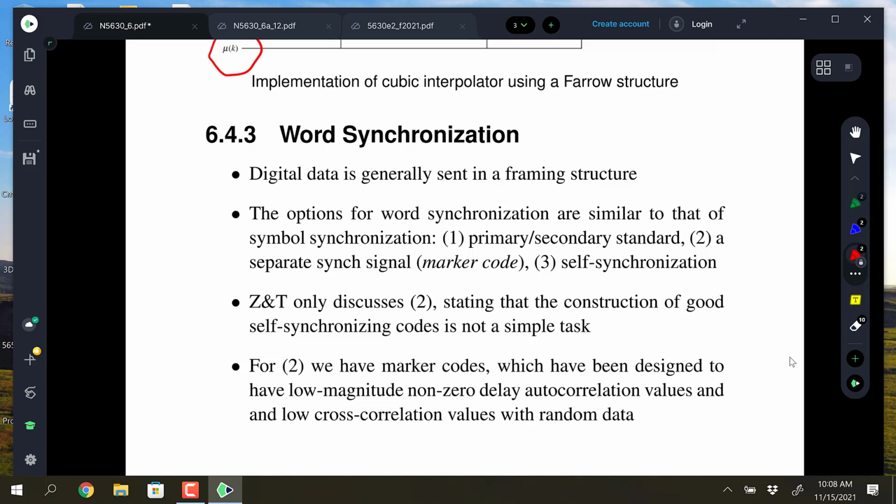In the system I was working on, I only worked on one of the most lowly Zigbee standards, the one that used BPSK. The one alongside it was MSK, but the BPSK one just had NRZ data bits, and there was a start frame delimiter that you had to look for right after you got locked up. There was also a fixed spreading pattern, and I guess that's how I did it, with the spreading pattern, because that pattern was either right side up, which is part of a Barker code, which was used in the original Wi-Fi. So that was part of that, I think.